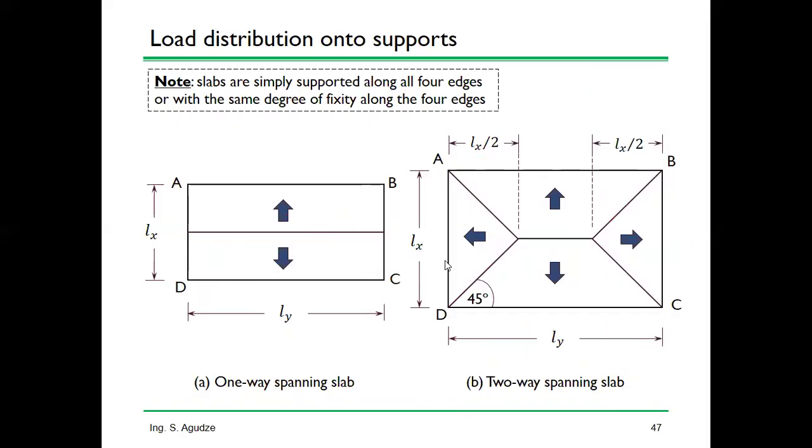Yes. Sir, please, what if the slab is semicircle? That is a complex loading. In complex loading, you have to resort to the proper yield line method of analysis. There's a way of sharing the load. But when you are learning design, you can't learn with semicircle. Oh God. So if it's a semicircle, there's a way this load can be shared.